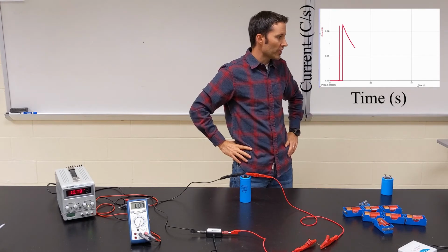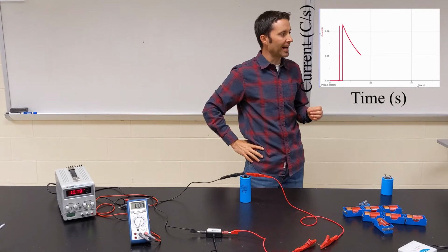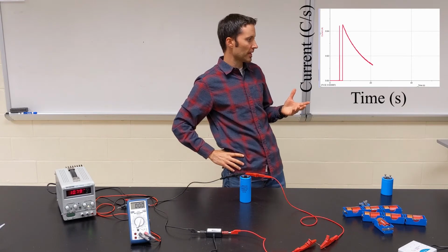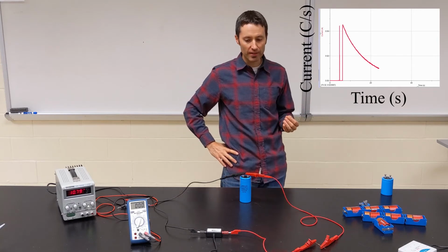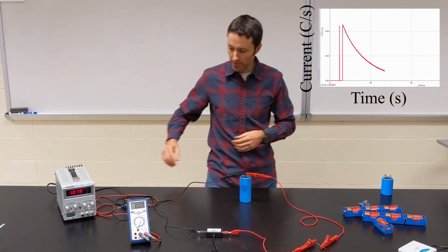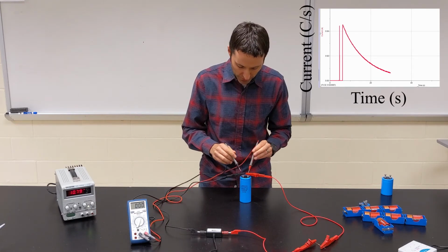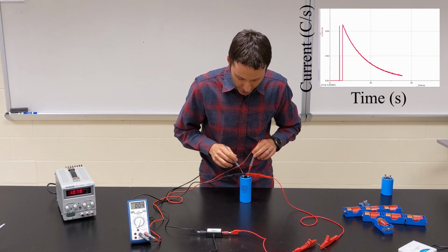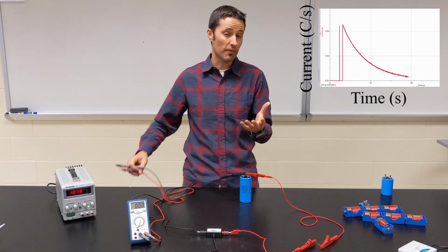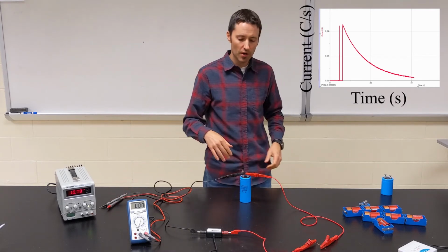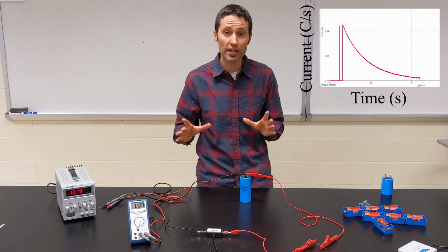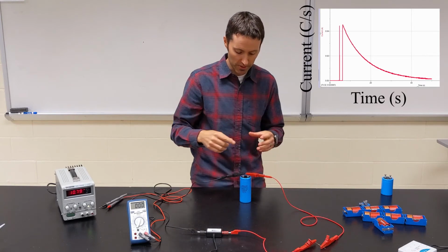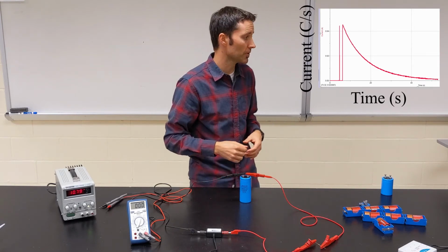You can see that the current, the amount of coulombs per second, was very high initially, and then as time goes on, now after about 20 seconds after it's been connected, there are fewer charges per second flowing through there. If we look at the electric potential difference on our meter, you can see we're down to about 0.3. The electric potential difference goes from what we started with, about 4.5 volts, and it'll eventually go down to 0 once all the electrons, the excess charge, have had enough time to move over to the positive plate, and everything becomes neutral.